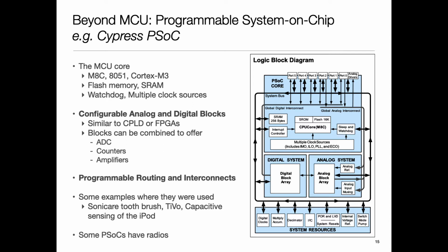You can think of it like that. So the name is chiplets, but little die. These are no longer packaged chips. They're just bare silicon die. You slap them on a bigger substrate, usually another piece of silicon, for example, and then wire them up. Companies like Apple, for the bigger processors, are using that because they can put memory and processors in the same way. But the use of this is a lot wider, in the sense that you can integrate all sorts of stuff, radios and optical stuff, all on these bigger substrates.